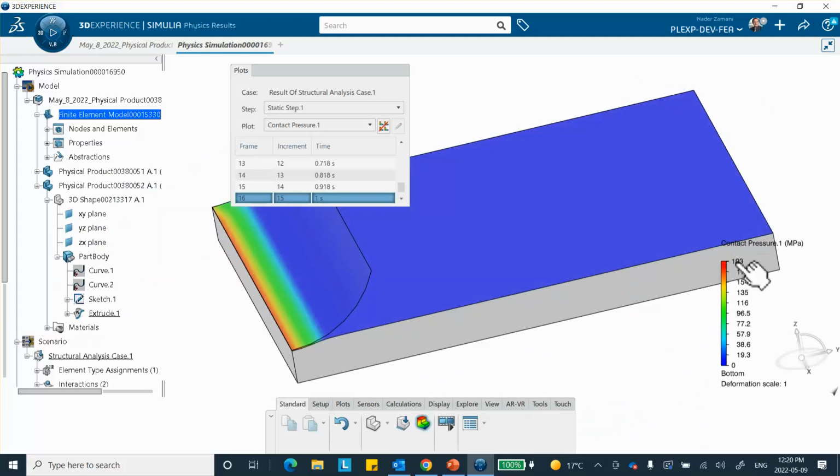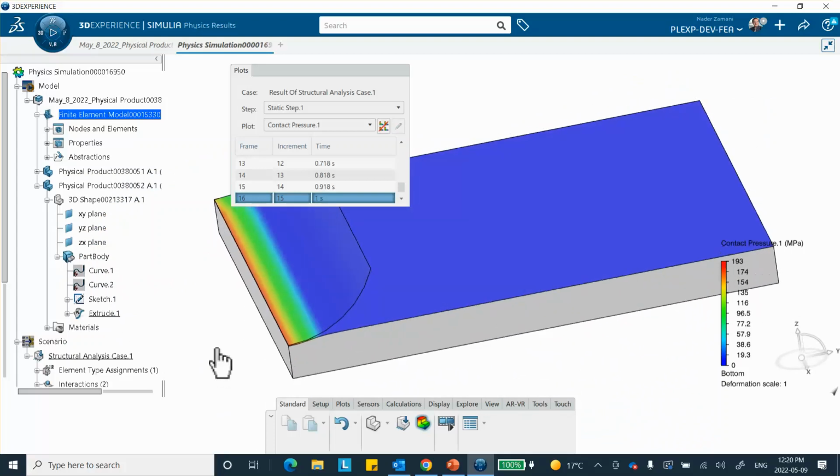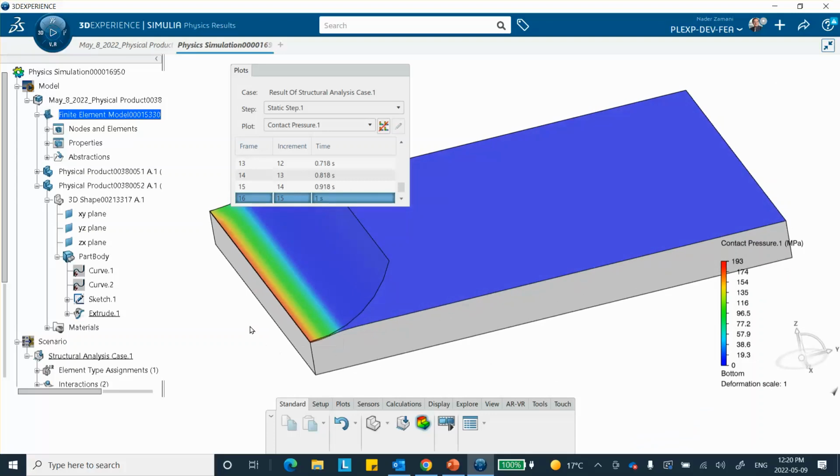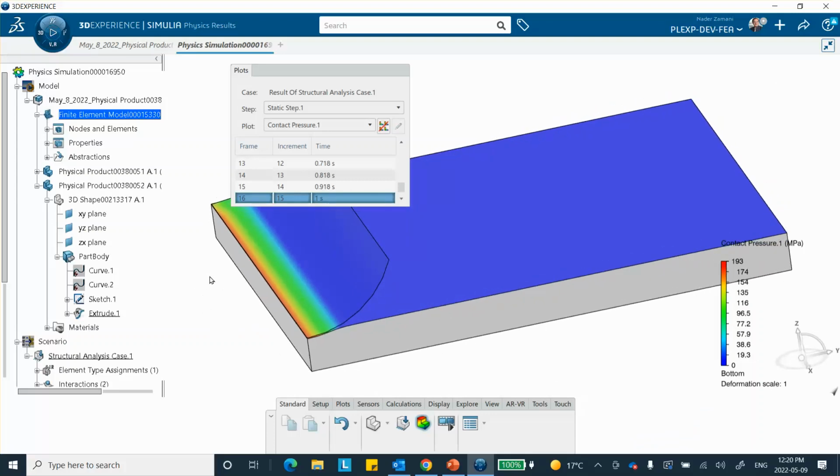These numbers don't match with the theoretical result because I don't know what kind of a mesh the fellow used in ABAQUS, and also really to be confident about the numbers, you have to do a mesh convergence study to make sure that this mesh is actually appropriate for the comparison with the analytical result.